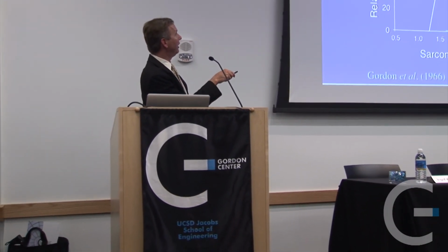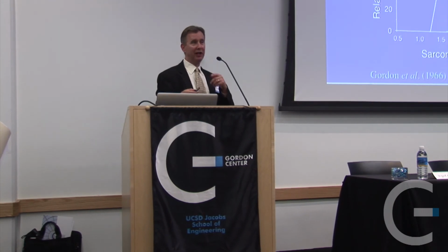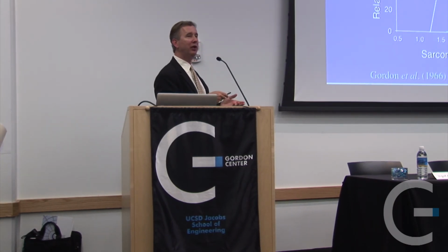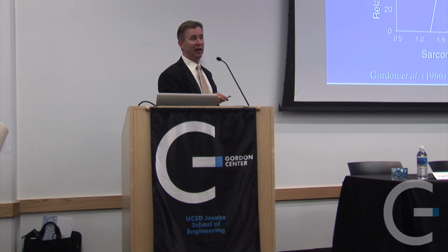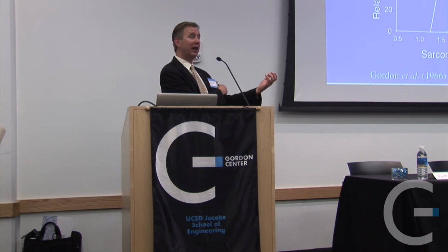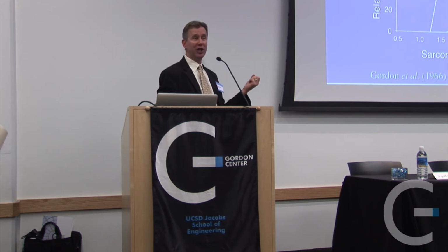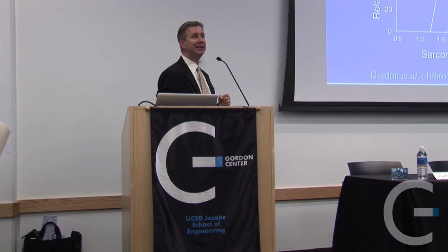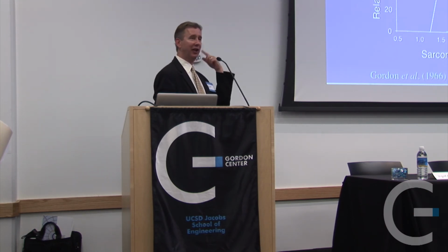Oh, okay. So that's a little bit of a tricky question. So I'll give you two answers. First of all, the number we use in engineering for the peak stress of a muscle is 250 kilopascals. But if you do almost perfect mechanics and you know the kinematics, say, of the elbow, and you do MR scanning of the biceps and brachialis muscles, so you know their dimensions, and you make really good calculations of the peak force or torque a person should be able to generate, they can typically generate maybe 60 or 70% of that. And that's mostly because you cannot voluntarily activate your entire muscle.